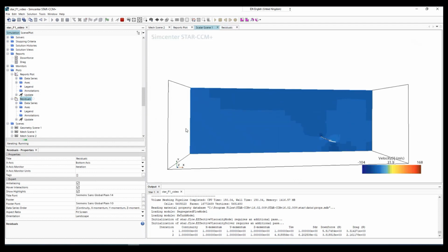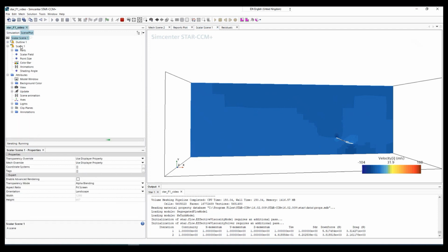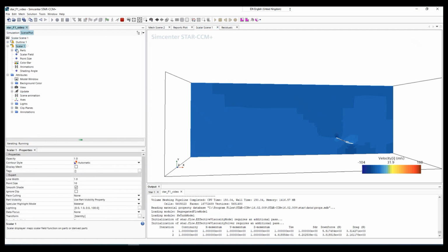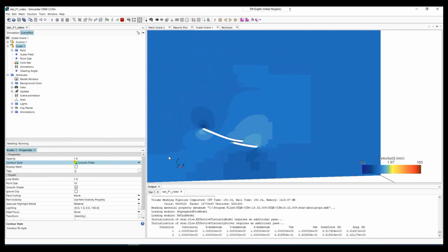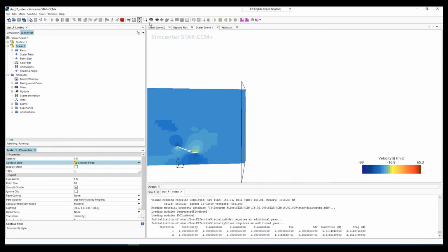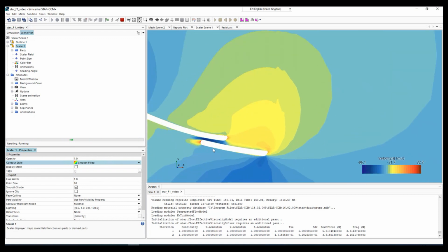And in the course, we can change the visualization in here. If we go to scalar and click scalar 1, which is x velocity, and we choose smooth, so the contour will show up in a better way, smoother. It's a bit more mosaic now, but we can change it to a smooth one. Takes a bit longer to respond. Okay, so we will keep it running, and yeah, you see this is a smooth contour.